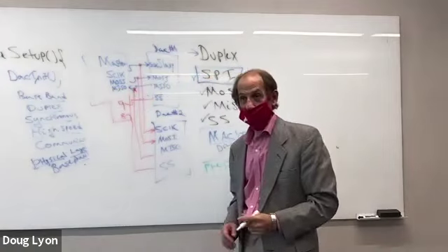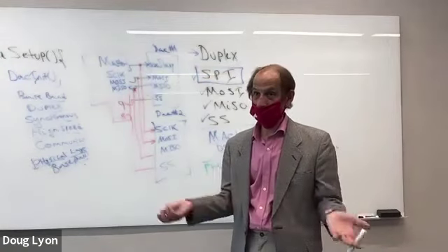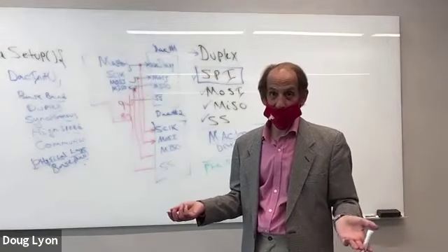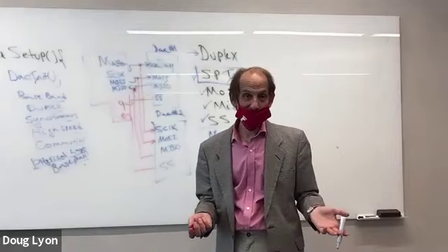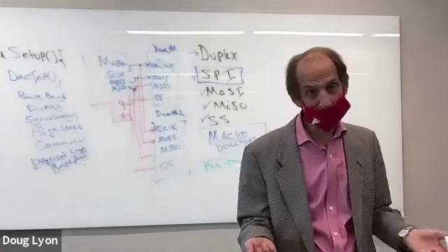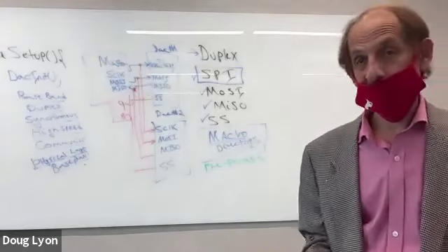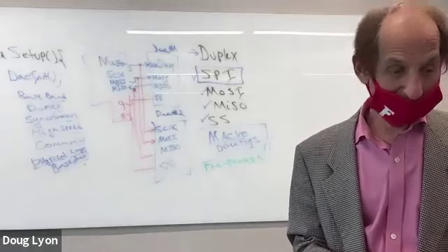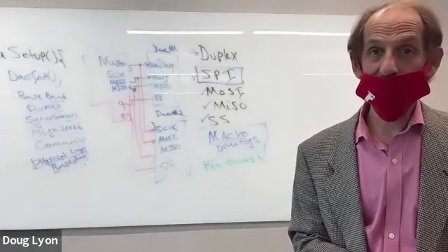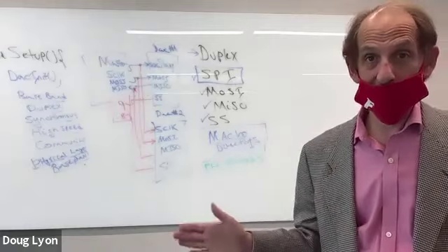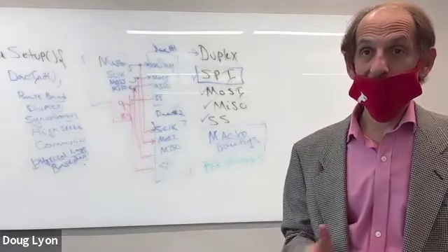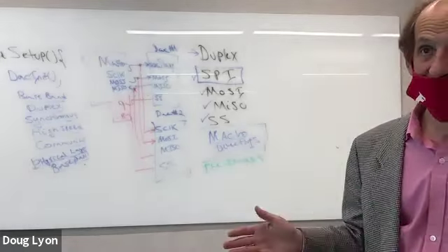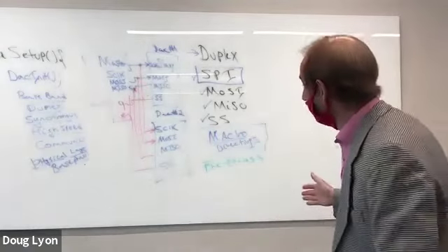And if I put a decoder in there, a 2 to 4 decoder, I can have 4 devices, but then I need a chip. I don't want to add another chip because it makes my cost increase. But maybe I could. I mean, if I had 3 bits, I could have a 3 to 8 decoder. And then the 3 to 8 decoder would let me directly address 8 different devices. But they have to take turns. I can't address them all at the same time because they're sharing a bus.